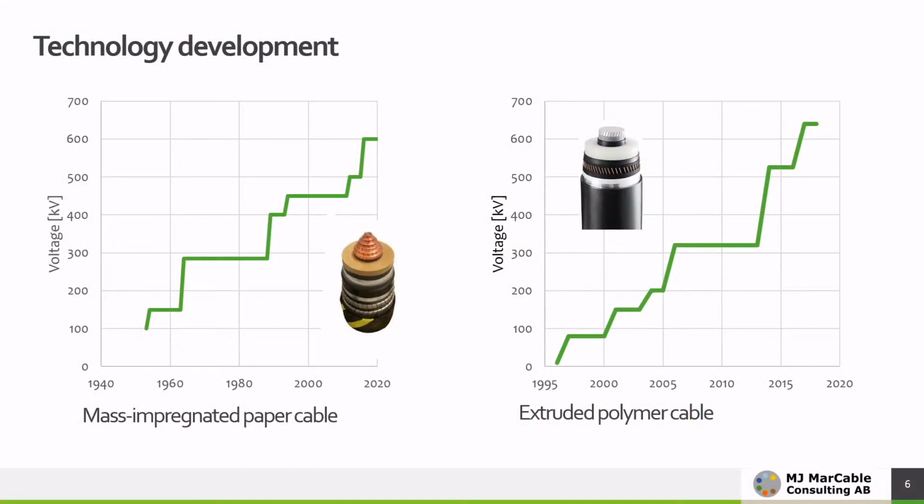And then what comes to the cables? In the beginning of the 50s, one had reasonable conversion technology available, and one had AC cables, which were typically paper-lapped cable types. At that time, there was no other type available. So it was really that simple: we have a lapped technology cable, let's try to put DC on it. And it seemed to work, proven very, very well up to today, because MI cable, which is a version of lapped technology, is still available.